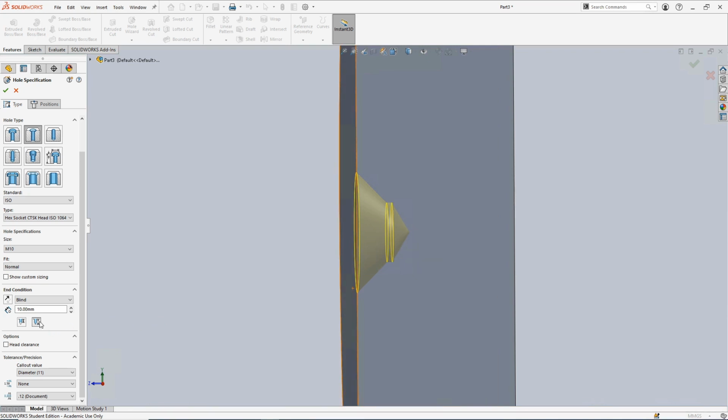But if I define depth up to the tip, it is basically the tip of the drill bit. That preview is representing a drill bit, and a typical drill bit tip would have a 118-degree angle. So you can either define it from the plane to the drill bit tip, or to the shoulder. It's far more common to define it up to the shoulder.